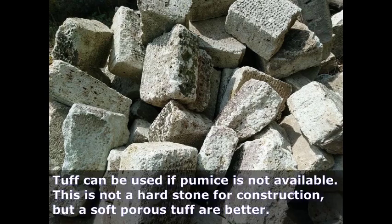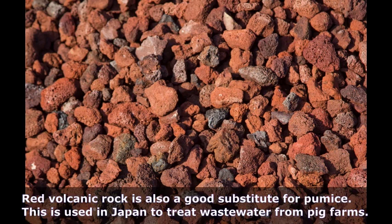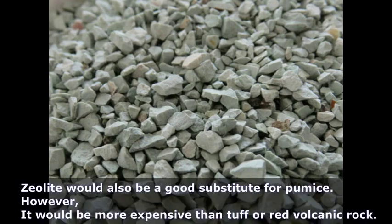Tuff can be used if pumice is not available. This is not a hard stone for construction, but a soft porous tuff is better. Red volcanic rock is also a good substitute for pumice. This is used in Japan to treat wastewater from pig farms. Zeolite would also be a good substitute for pumice. However, it would be more expensive than tuff or red volcanic rock.